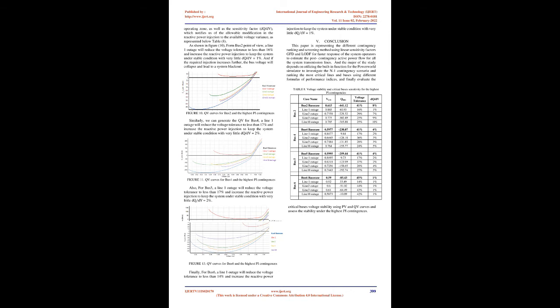Finally, to determine the most critical and sensitive bus, we apply the complex performance index represented in equation 7, as shown below. As a conclusion from Table 7, we notice that the most severe outage affecting the system drastically and leading to a blackout is the outage of bus 2 with PI complex equals 19.44 due to 3 line overloads, 1 bus going under voltage limits, and 7 other elements going out of service, as shown in Figure 2. Also, we can notice the performance index ranking procedure is totally independent in determining the critical cases, regardless of the number of disturbed elements or exceeded limits.